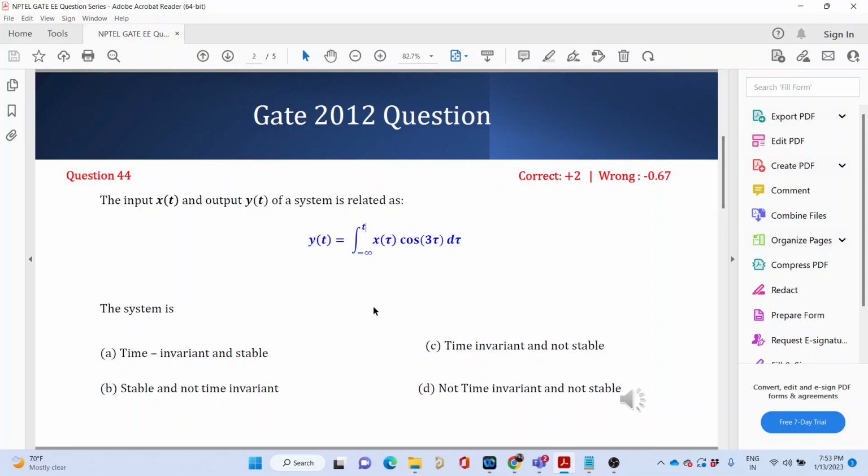So for bounded input, output will be bounded. Correct. What does bounded mean? It will have a definite amount of input, not infinity. Okay, so you want to say that a signal is bounded when it has a finite value at any instant in time. Correct? Yes, sir. Okay, good. So you are saying it is a stable system, so it is never going to give you infinity.